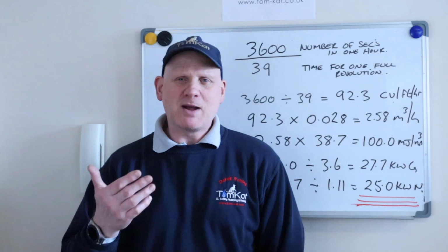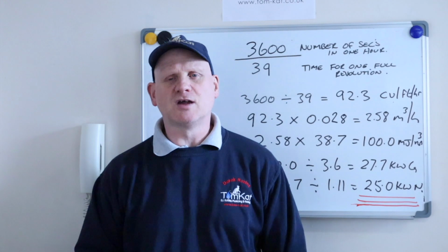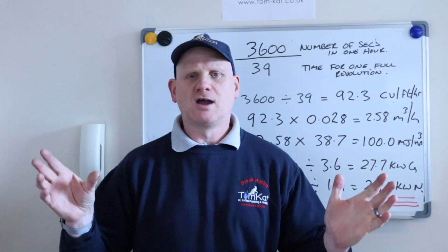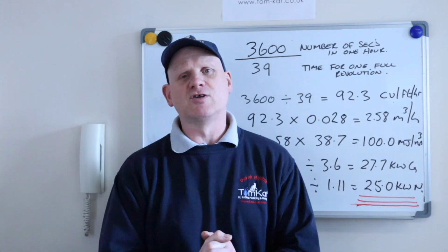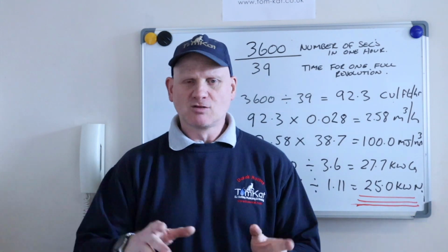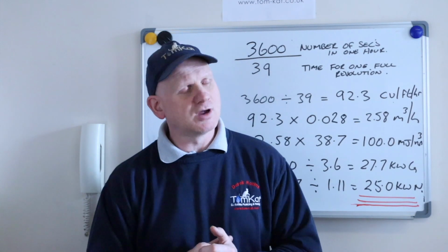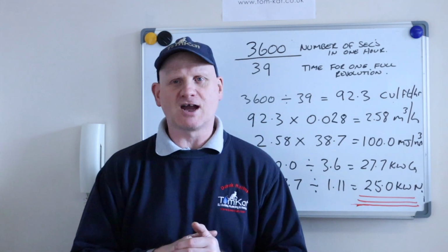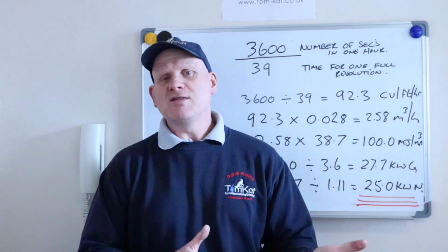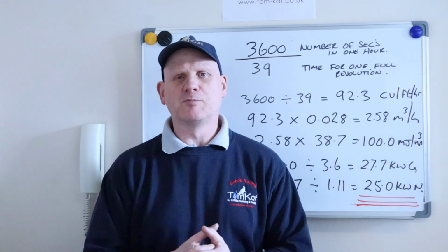Now, again, depending on the time of the year. So in the summer, when the incoming water is warmer than it is now, because we're in February, your delta T is going to be different, okay? So your boiler might not have to work as hard. So if you can preheat that water coming in, it won't need to work as hard than the boiler when it's gas rated. So it depends on the time of the year, okay, and it depends on the output of the boiler.